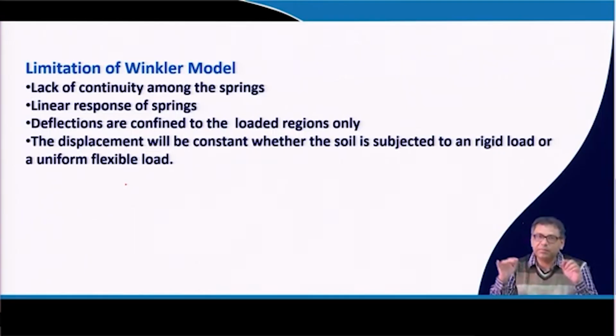The deformation will be beyond the loaded region also, and within the foundation also. But as there is no connection between these springs, the deformation will be only in the loaded region. It will not be beyond the loaded region. But actually in a foundation, the deformation will be in the loaded region as well as outside the loaded region.